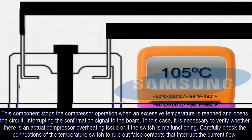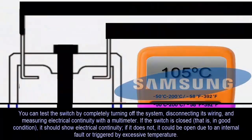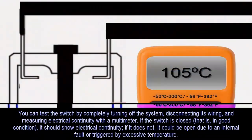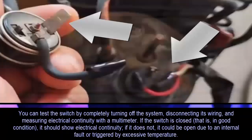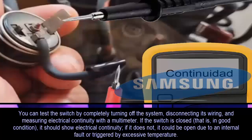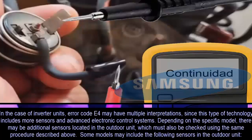Carefully inspect the connections of the temperature switch to rule out false contacts that interrupt current flow. You can test the switch by turning the system completely off, disconnecting its wiring harness, and measuring electrical continuity with a multimeter. If the switch is closed, that is, in good condition, it should show electrical continuity. If it does not, it may be open due to an internal fault or triggered by excessive temperature.